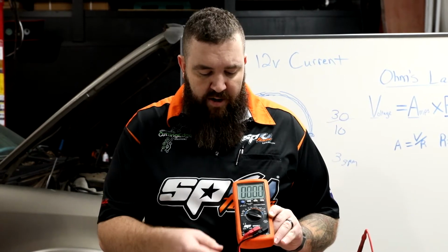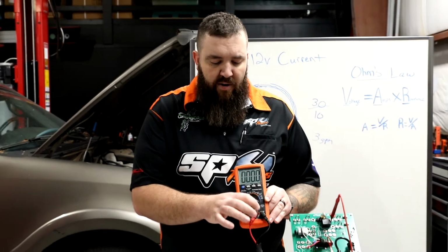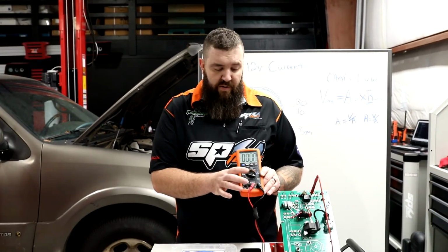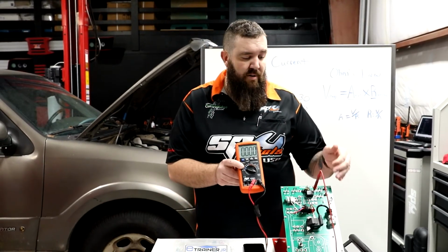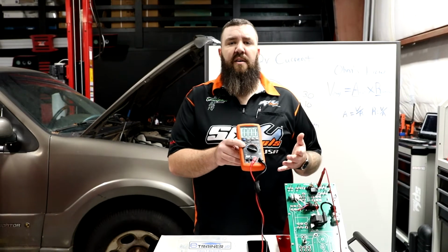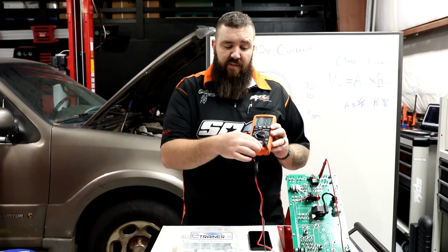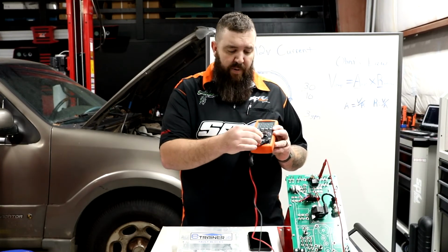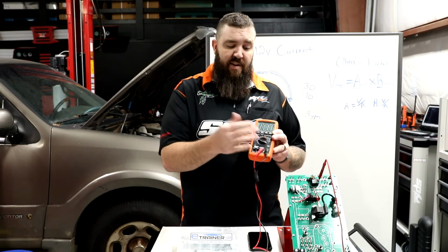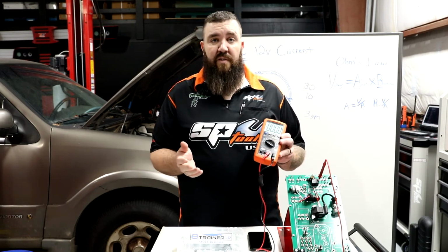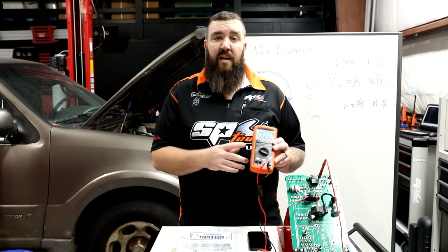We've got the meter turned on, we've got our leads here put into our positive terminal and our COM or negative terminal here on the meter. So what we're going to be doing is showing you how this functions in relatable terms to DC voltage. You've got to think of your multimeter as just a fancy automotive calculator. All it's going to do is take your voltage reading from your positive post and the voltage reading from your negative post and subtract the negative from the positive. That's all it's going to do.